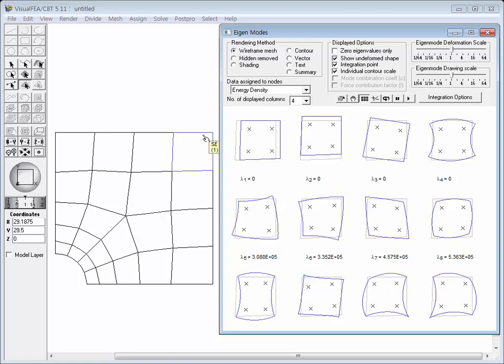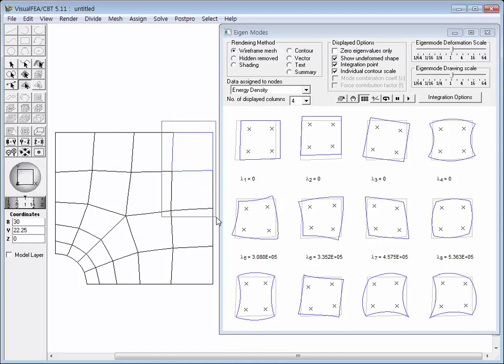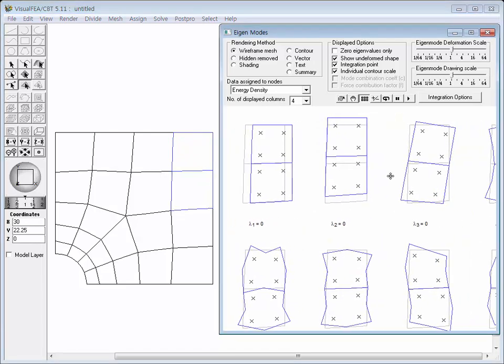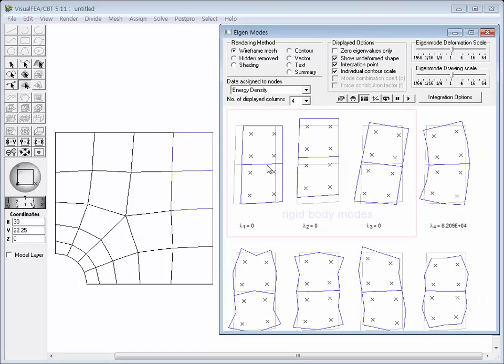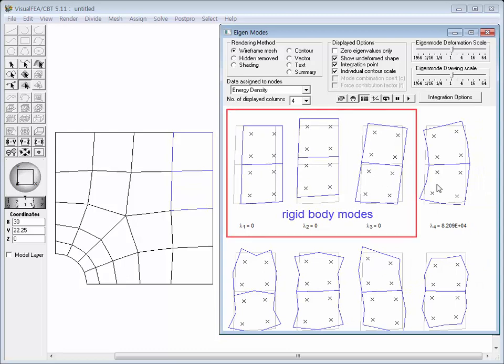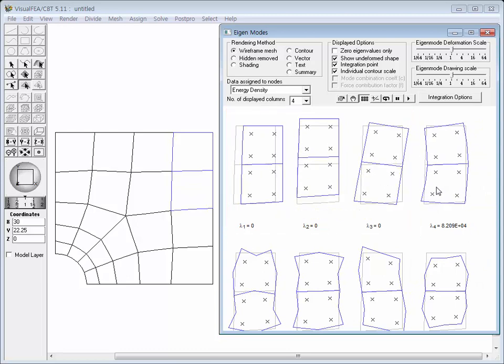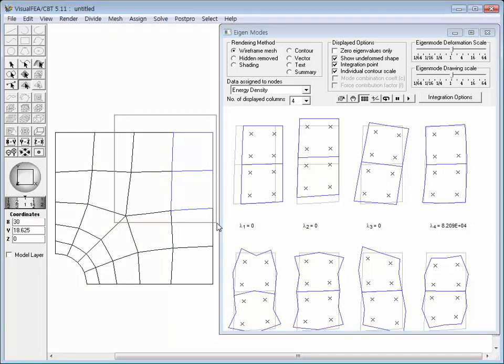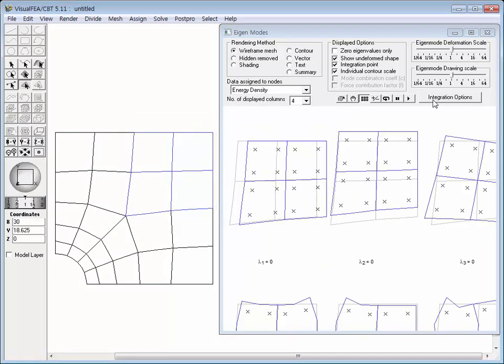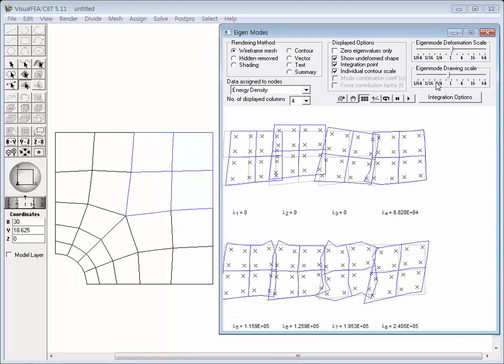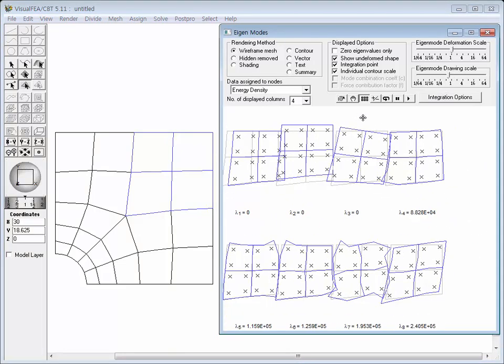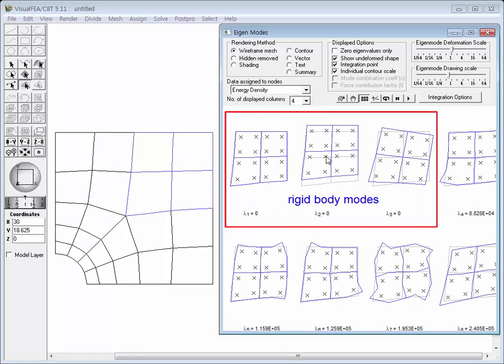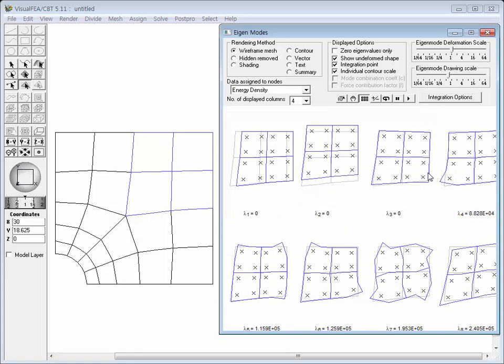Let's examine the eigenmodes for assembled configuration. Select 2 adjacent elements. This time, there appear no zero energy modes. It is because both of the elements cannot display the same spurious mode while they are connected. This is an example of non-communicable mode. Let's examine the case of 4 elements. Assembly of 4 elements also shows the same aspects of rigid body modes without spurious modes.